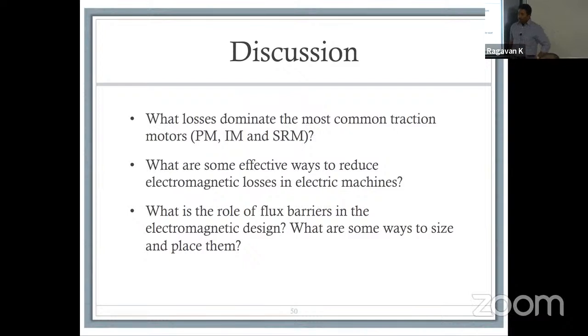For that, only that point. We have seen the motor of BMW i3. At the corner of the rotor, there are only tiny parts where the flux can flow. It might cause saturation at that point if we remove too much material from the rotor. Correct.